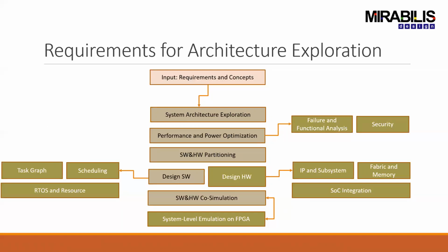And at that point, you know exactly what is going to be the minimum latency or the highest throughput that I can actually achieve. At that point, you start moving into hardware-software partition, meaning that you're looking at how do I split this data across multiple subsystems or across multiple IPs on a chip or across multiple boxes. And of course, that's where you start dividing into portions of software and hardware and start selecting different components, scheduling the RTOSes, and you assemble a complete system.